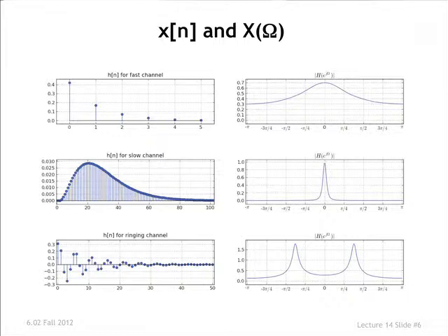All right? And I'm just plotting the magnitude. Ignore these labels. These are the same figures you saw earlier for little h and big H. I'm using them again, except now I'm thinking of this as a signal, and this is its DTFT. This is a signal, x of n, and this is its spectral content. All right, the relationship is exactly what we had with frequency response.